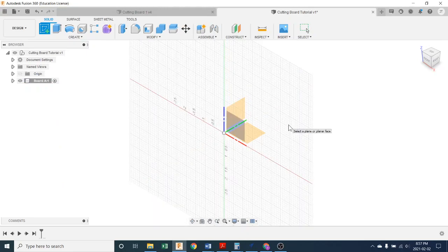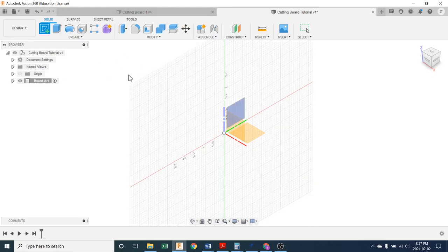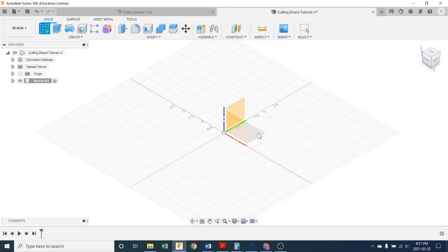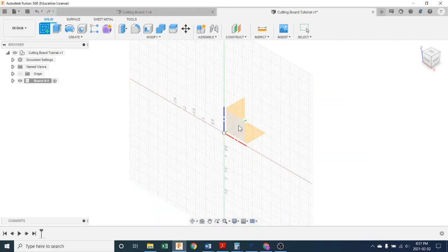We draw a two-dimensional sketch. It's like a piece of paper, and that's how this is going to work. We're going to draw two-dimensional sketches, and then we're going to do what they call extrude those into three-dimensional bodies. So when you click start a sketch, you have to pick something to sketch on. So because I have nothing drawn yet, the only thing I can sketch on are these, what they call planes. So these are planes that represent the three dimensions in space.